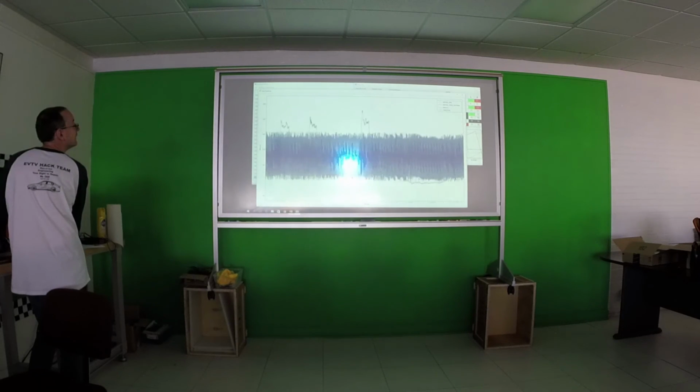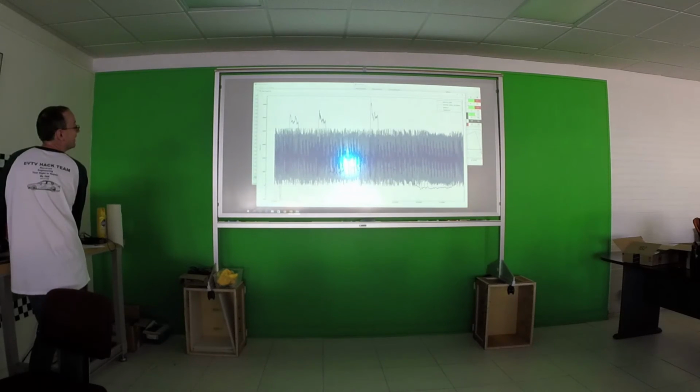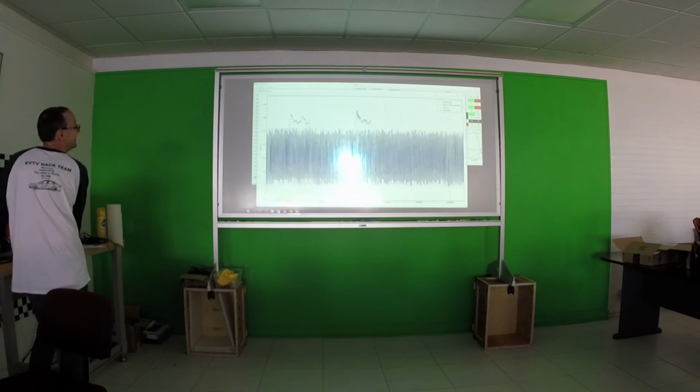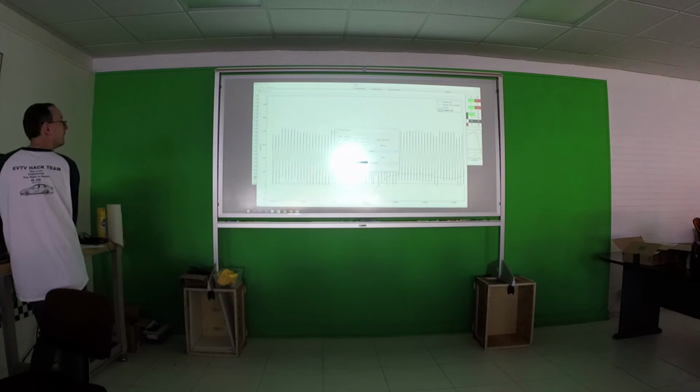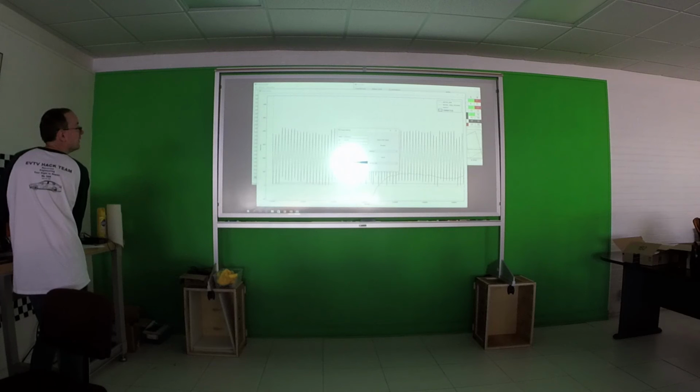Really? Offset. I thought the throttle isn't stored right in the DBC file. Yeah, he was on the throttle an awful lot. Like a Super Bowl clock full. The right foot of a Formula One guy. Oh, yeah, it's not set right. Byte 6. It's just byte 6. There we are. So that's throttle.